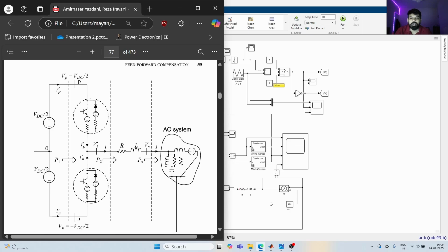We're giving it 400 volts, but here we will have some inductances, some capacitances. These are all system impedances, which will basically represent a realistic AC system with its characteristics, and we'll try to model this in our model and see what impact this realistic AC system has on the dynamics of our converter control.